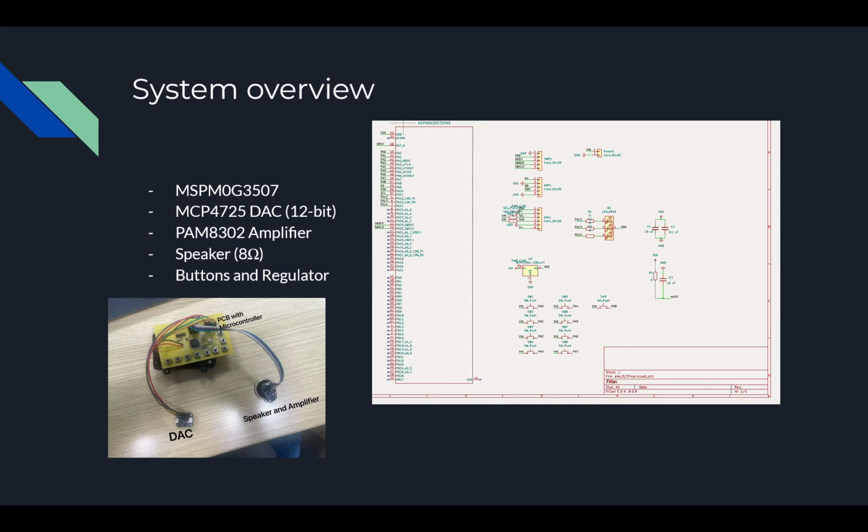Each button is connected to a GPIO pin on the microcontroller with an internal pull-down resistor to detect rising edge inputs. When the button is pressed, the power voltage is connected to the corresponding GPIO pin. The microcontroller computes the digital waves and outputs the signal via SDA to the DAC. We also added an active low LED to indicate the stage of the microcontroller we're in. We also added capacitors to prevent power noise near the microcontroller.